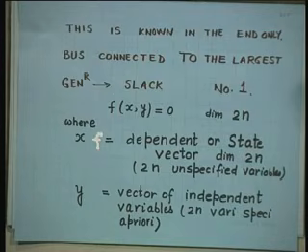However, this is known in the end only when you solve the network. So, that is all right. So, losses are the last item on the menu when you solve a load flow problem. As I told you a couple of minutes back, the bus connected to the largest generator is normally assumed to be, or considered to be, a slack bus, and it is always called either the 1st bus or the nth bus, just for convenience.